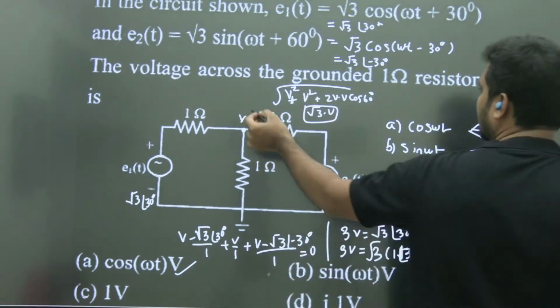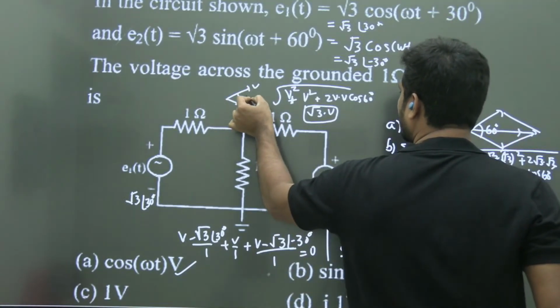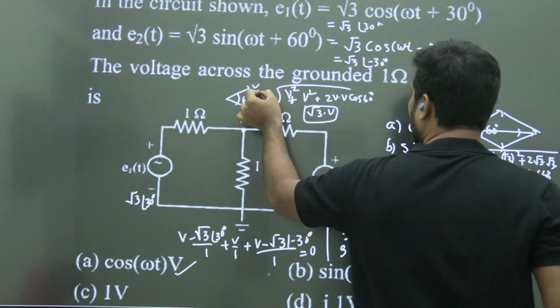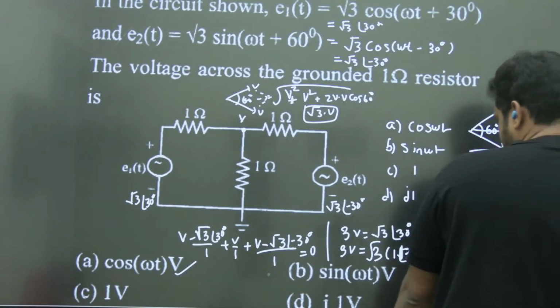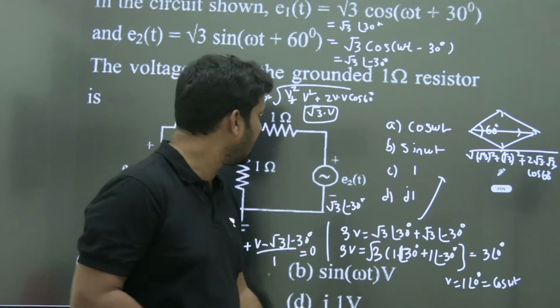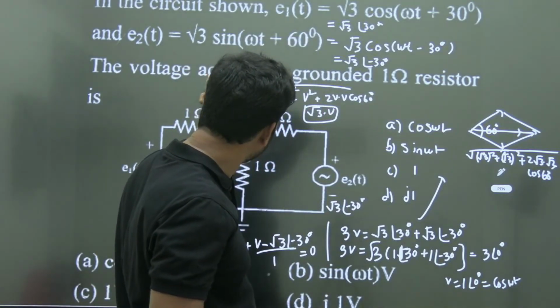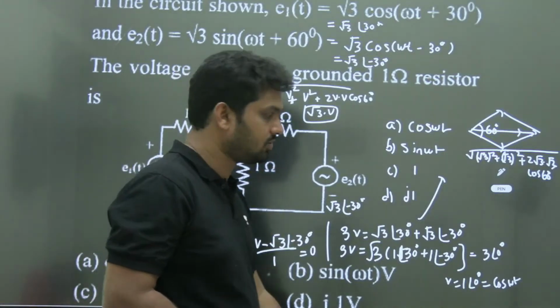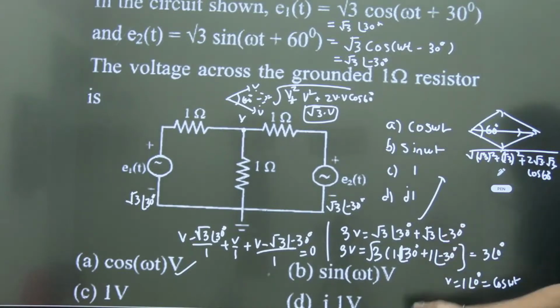When you have this magnitude of v with 60 degrees phase shift, the resultant is like this. So this will be √3 into v. The angle will be the median of both, that is plus 30 minus 30 का बीच में median angle will be 0 degrees. Okay, you can do by normal rectangular conversion and also do the addition, nothing wrong.